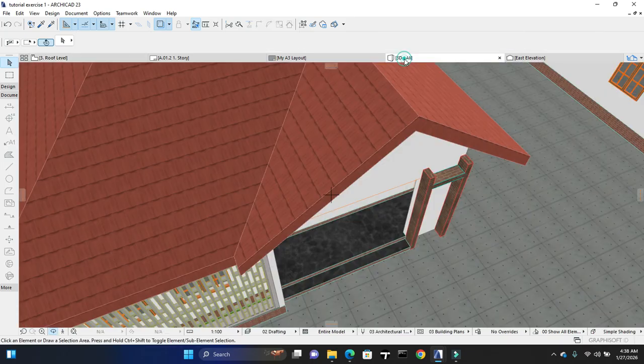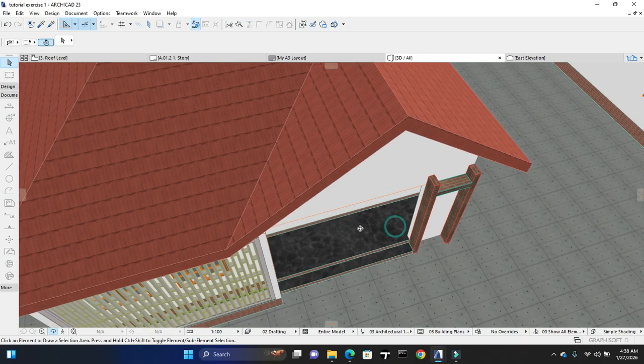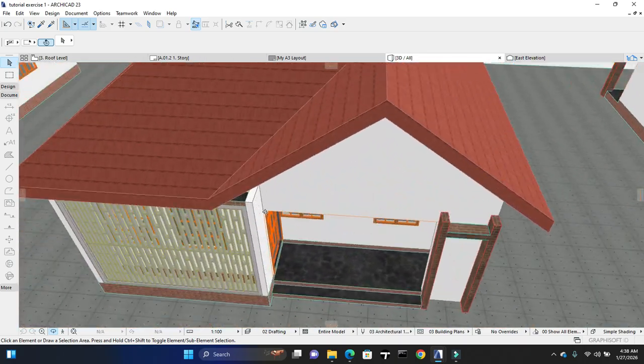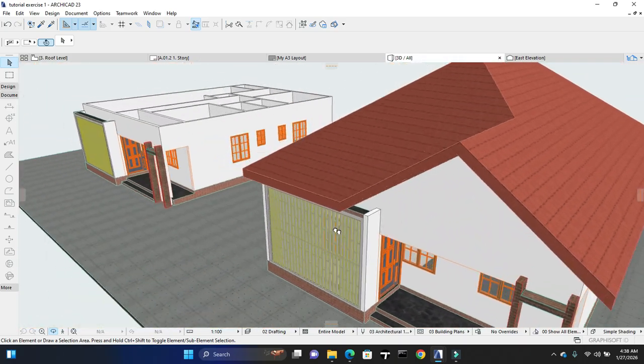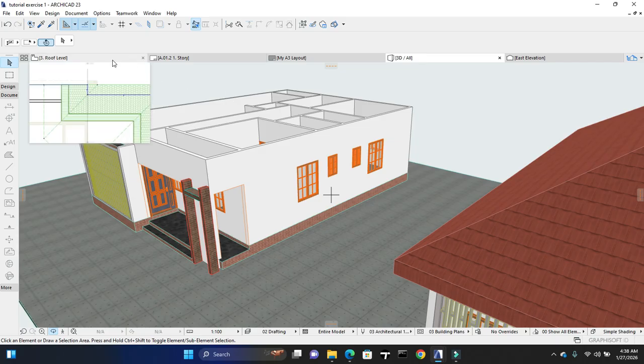Now click on the single line geometry option. With that being said, the first thing they say is interface node of pivot line. So that's kind of like your base line of the flat roof, the lowest line of the flat roof. So I want it to tilt to the back, so the lowest line of the flat roof is at my back. I've drawn the line.